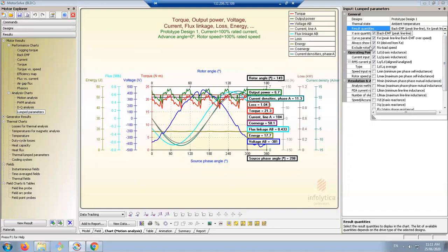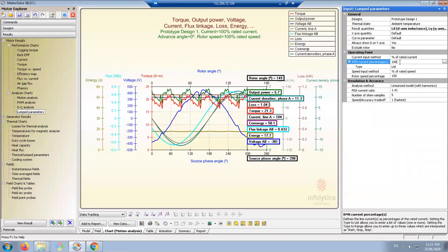Just one single thing. As I said, we have a nonlinear system, meaning magnetically nonlinear, meaning that by changing the motor excitation in terms of current level, you will observe different inductance levels. Let's see how LD and LQ, the two inductances, will change if we change the current.